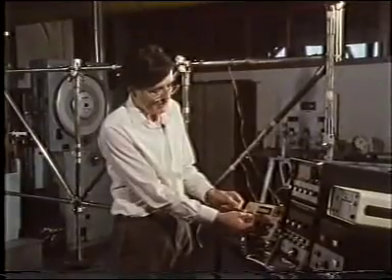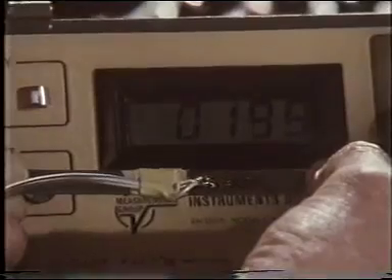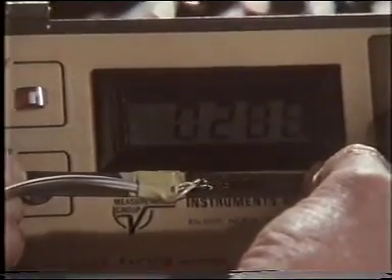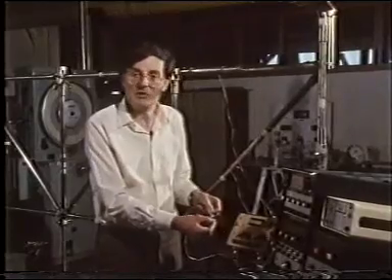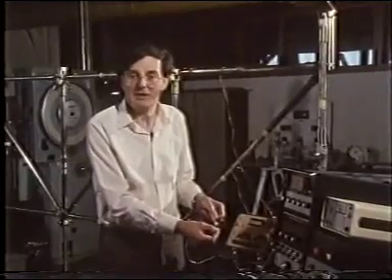As you can see, if I were to apply a tension force to this, the reading comes quite high, and the effect is amplified by the fact that the strain gauge is in a zigzag like this, thus increasing the length and increasing the resistance effect. Of course, this is just acting like a spring, which you've come across previously in the course. And for a spring, the load is proportional to the extension.